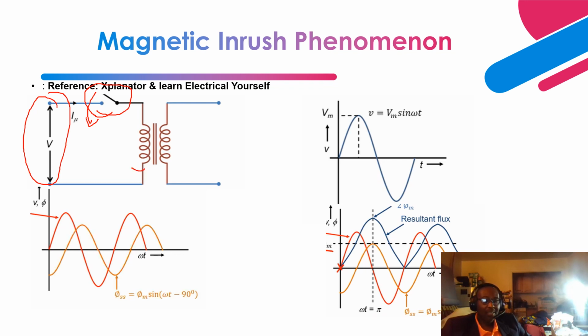Once this voltage is applied to the high voltage winding, this is the high voltage winding over here, we have a current that is going to flow, and that flow of current through the core creates an electromagnetic field. That electromagnetic field is going to go through the conductors of the low voltage winding and induce a voltage here. But in this case, our secondary is open circuited.